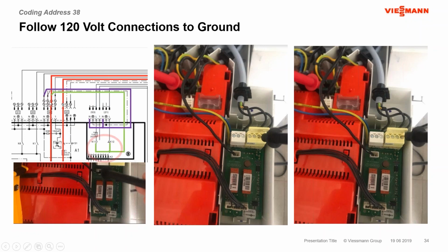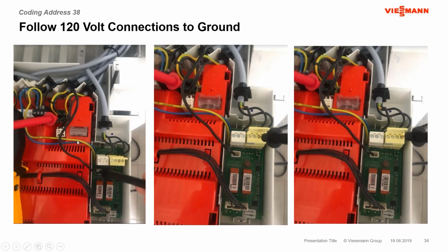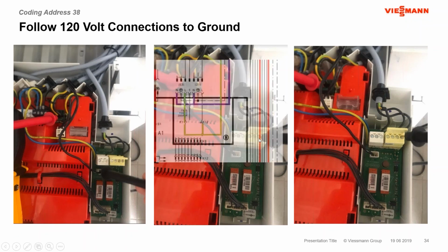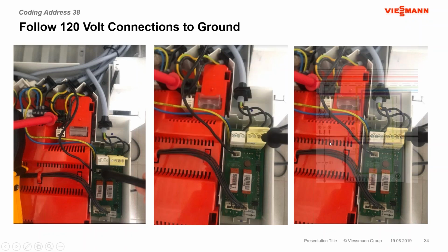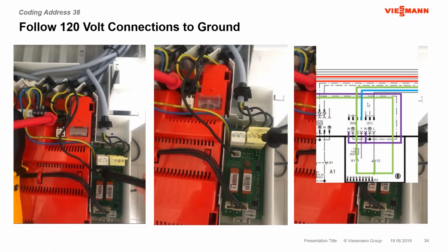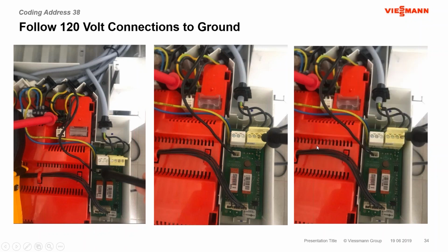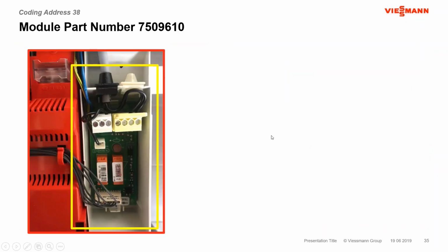Do we have power here? Measuring it. That goes over to our relay contacts. So we're checking down here from ground to the voltage on that connection there. The 53L to ground. Do we have power there? And then we'll check over here at the 1 to ground. Is there power there? If there's no power, somewhere in there it's interrupted, that would indicate that the board here, our expansion board, is our issue.